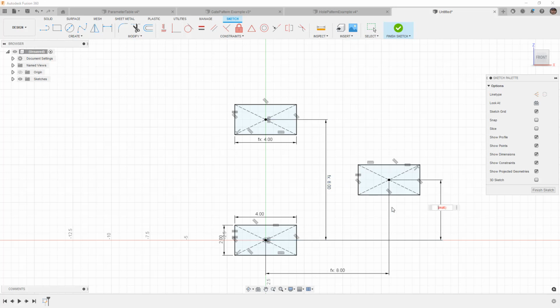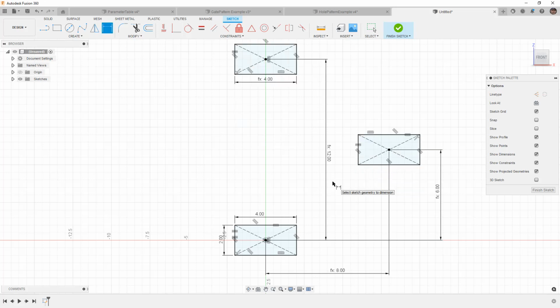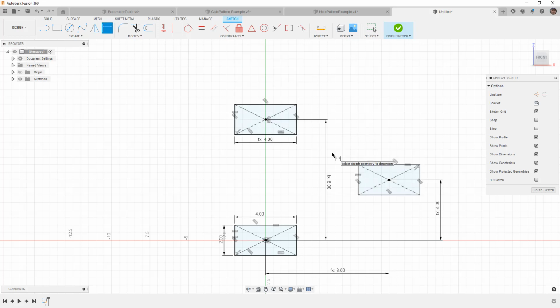We're going to put it in some brackets. And then we're going to divide it by 2. Now, remember that this is D6 and not D4. We want to make sure that we only use this value here. So we're going to divide it by 2. And now if we decide to change this formula to say, let's multiply it by 3, now it's going to move evenly. So again, just because a dimension works out in this instance of a sketch, you have to really think long and hard about how you want your designs to update.